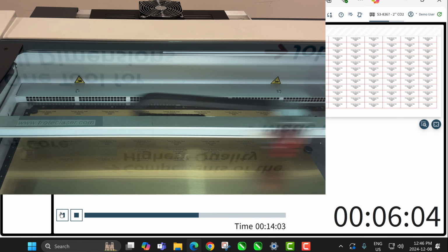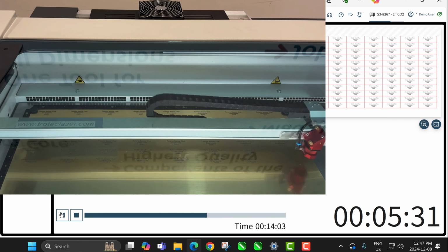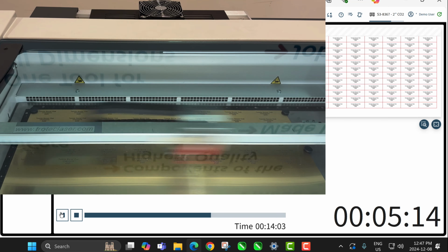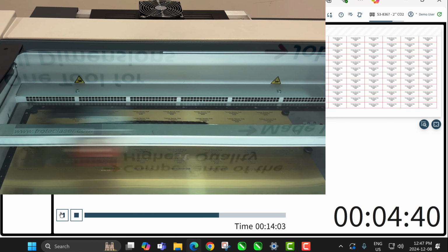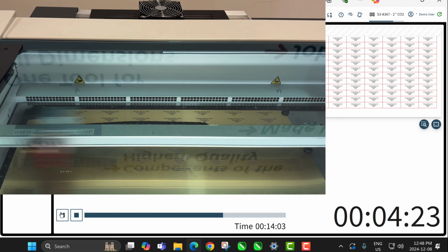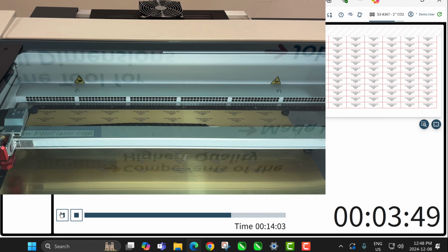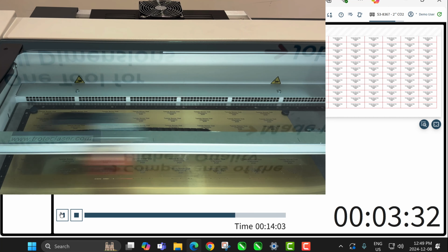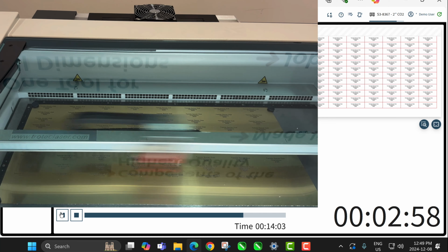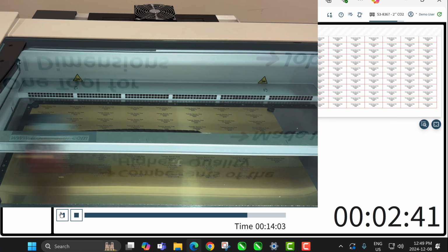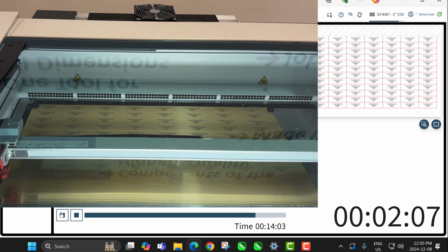You can also see that I've got magnets attached to the edges of the laser thin material here, because I can't use the normal engraver's table tape like I normally would, and I don't want to use masking tape. I could use masking tape because I'm not getting that much, but I like to use the magnets just in case. The table is stainless steel, so the magnets will work on it, no problem. If you didn't have a stainless steel table and you just had a cutting grid there, then probably what I would do is just buy a 12 by 24 sheet of stainless steel. We sell it here, 15 thou. Put it on there, put the material on the 12 by 24, and then use the magnets that way.